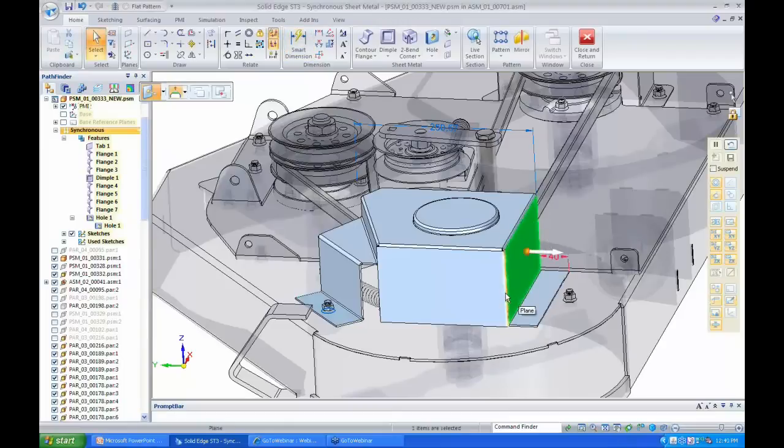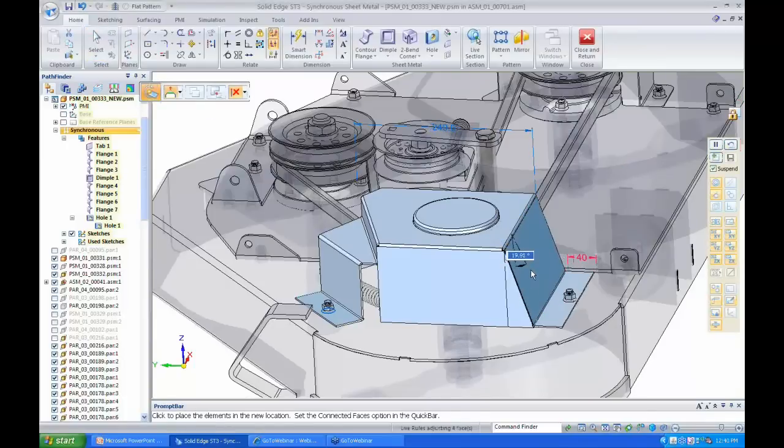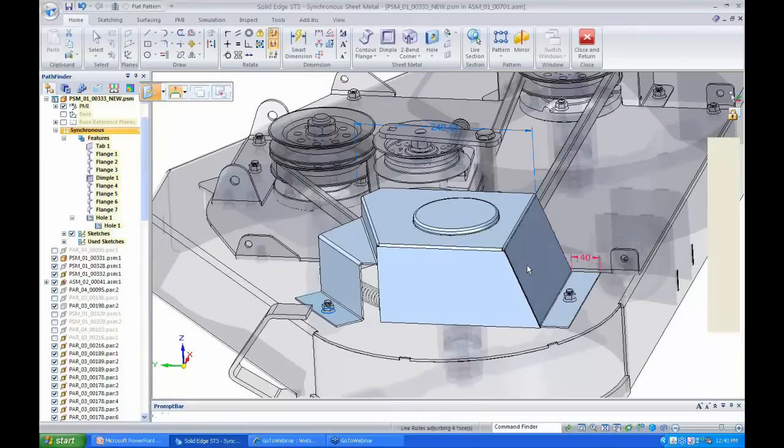So in this case, I'll select multiple faces so that this face on the left hand side also comes around with the taper angle. I don't want any coplanar faces, so for that purpose I just turn my labels off. So now I can define the angle of my rotation, and you'll see that it took care of the other side flanges. Now we're all set. Now we'll just repeat this another step here to get this bolted cutout here, and then put a small hole.